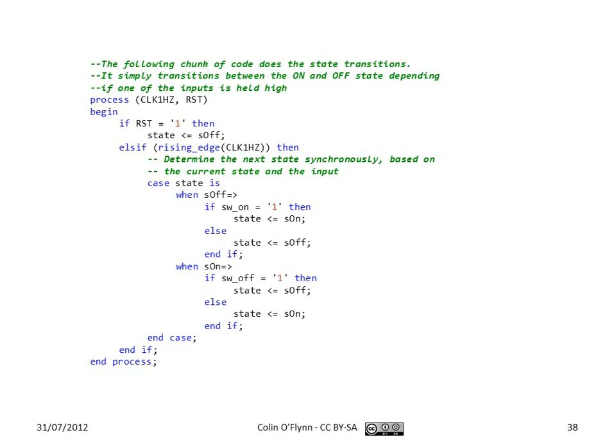For the logic to do the state transition, we add: if the clock changes or the reset changes, run this process. If reset is 1, we go to the off state. Otherwise, every time there's a rising edge of the clock, run the following. Only on the rising edge; on the falling edge, don't do anything. It's a case statement: what's the current value of state? Is it S off or is it S on?